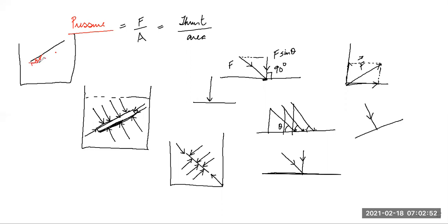It's applying so many kinds of forces on the surface, and this point also is applying a force like this on the surface, and these forces cancel with each other. So what is left is basically only the perpendicular component. So you think about this more, and you understand that the liquid all around the surface will only exert pressure perpendicular to its inclined surface.